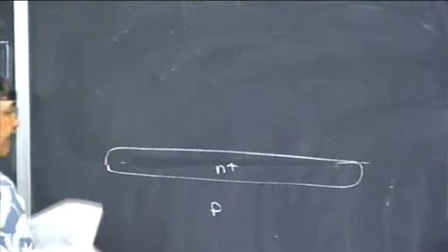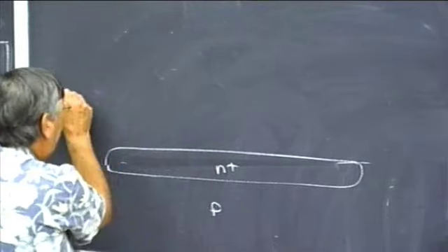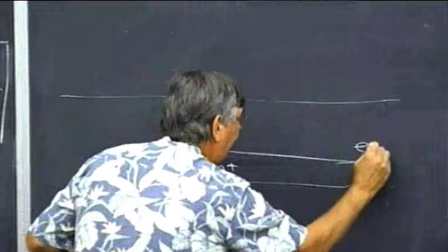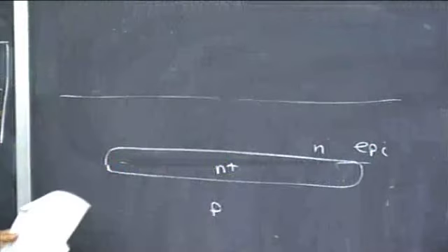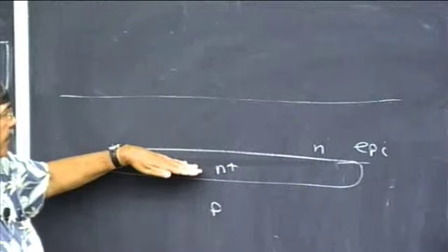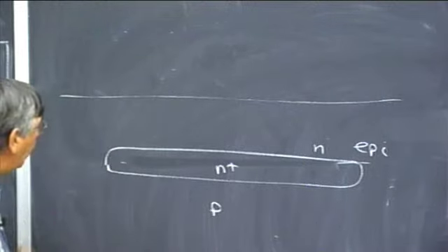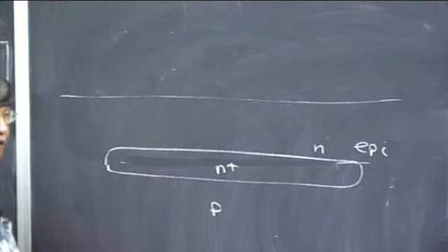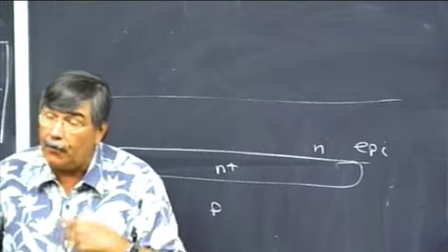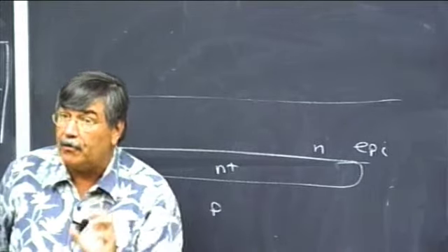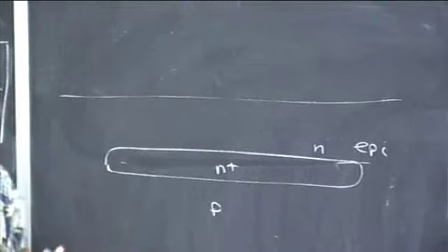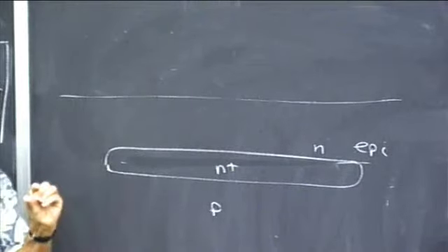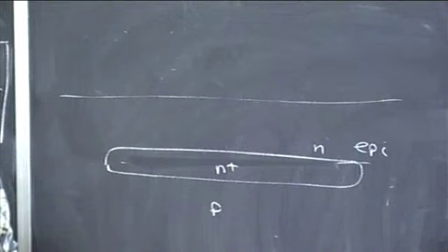All right. Then we're going to grow an epitaxial layer. Epi, so this is similar to the other process. This is the N- epi collector. Now, 20 years later, these regions can be much smaller. They're probably more heavily doped. Heavier doping on the less heavily doped side means smaller regions. Smaller is better. Okay? As time goes by, the doping levels get higher. The depletion layers get narrower. Okay? But things are smaller.